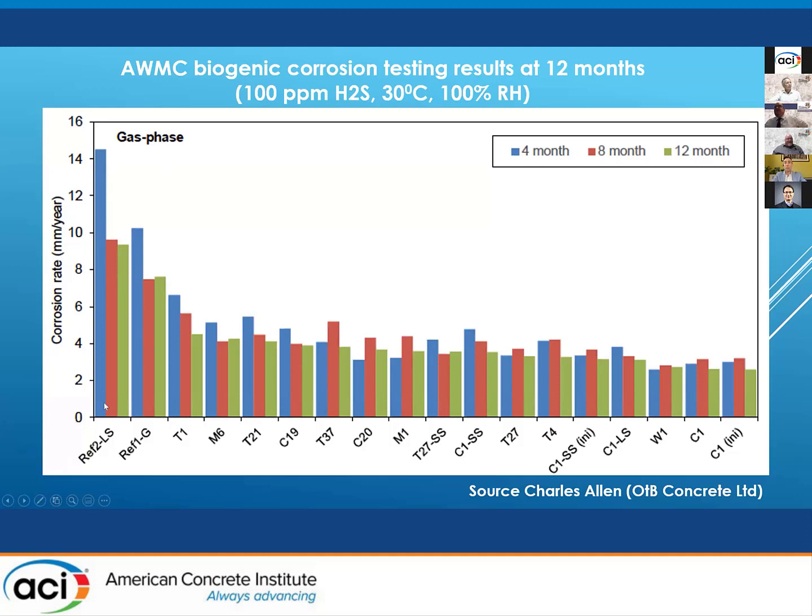This was with a limestone-based Portland cement system. This was a granite-based, so that's contrary to a lot of the information out there that you'd be using limestone. The bulk of these mixes that have been looked at here are using 80% slag replacement.